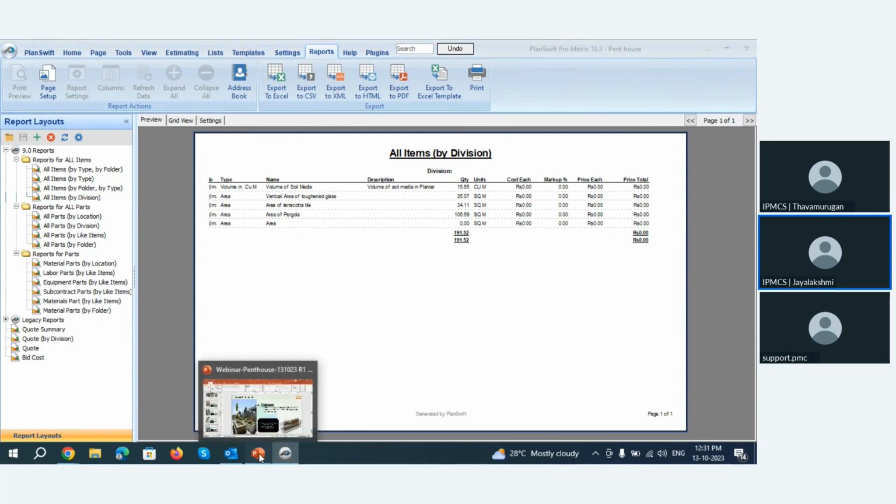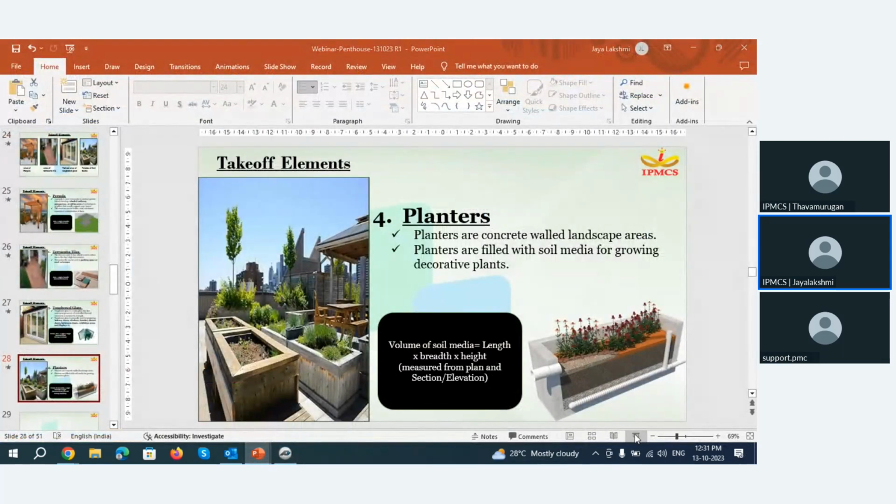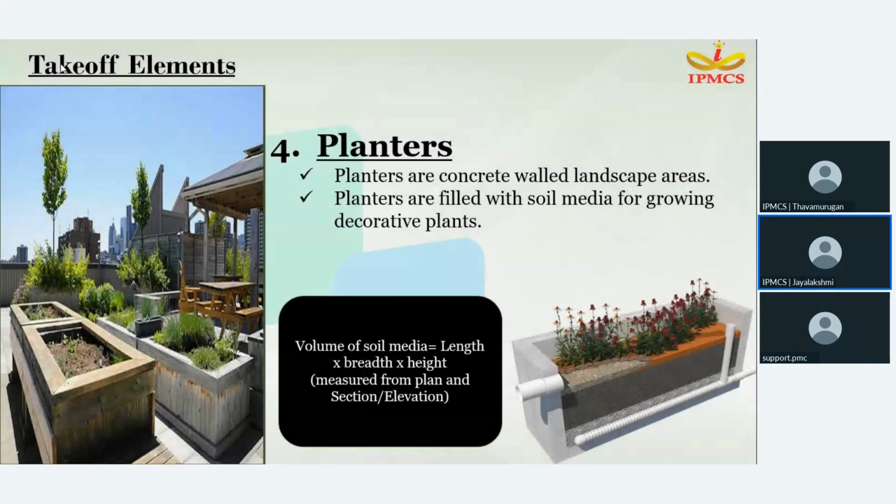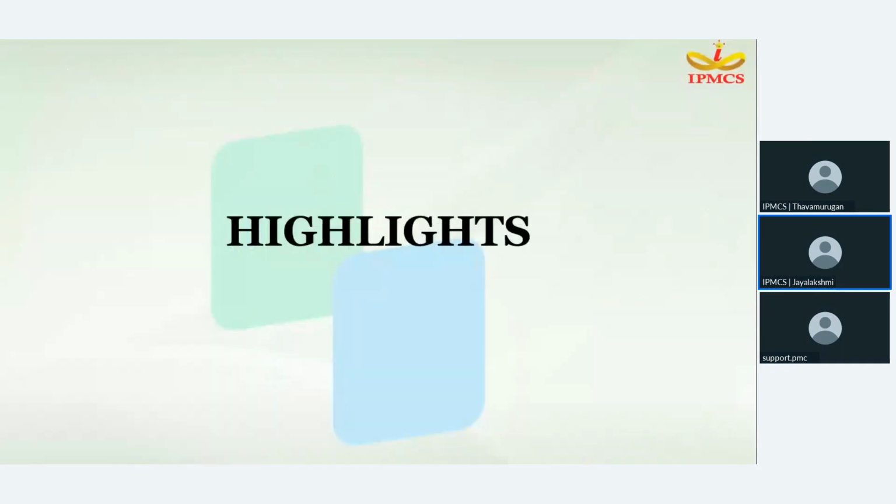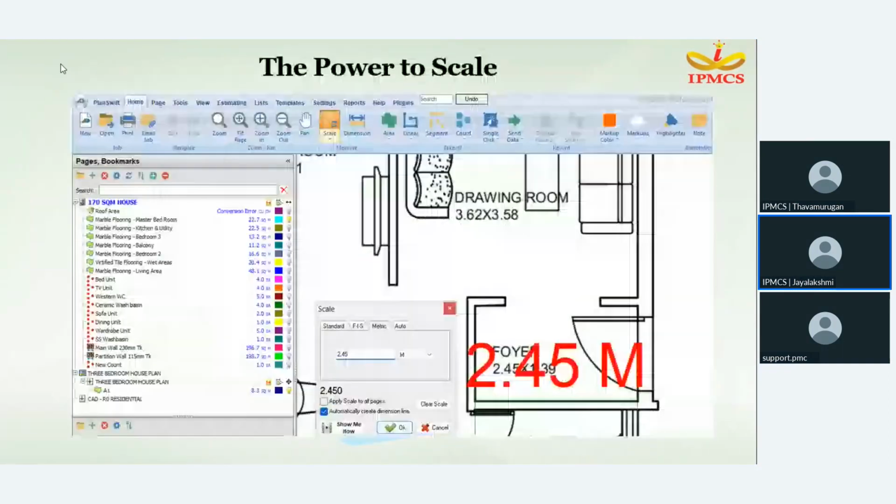Let us get back to the PPT. So let us discuss other highlights of PlanSwift. PlanSwift has its own scaling facility. So whenever we are adding a drawing, we can scale it accordingly. Even if we don't know the scale of the drawing, we can use the scale property inside PlanSwift to scale it using a known measurement inside the drawing.